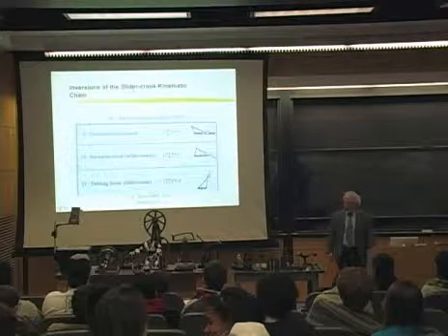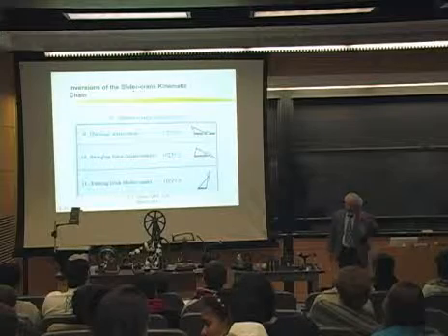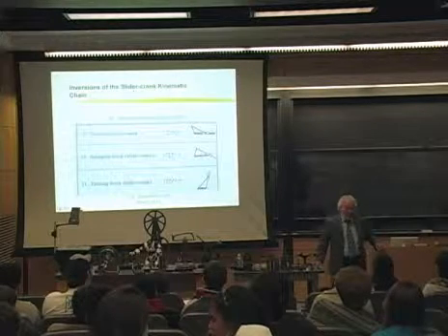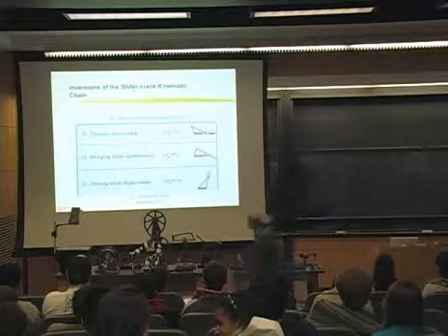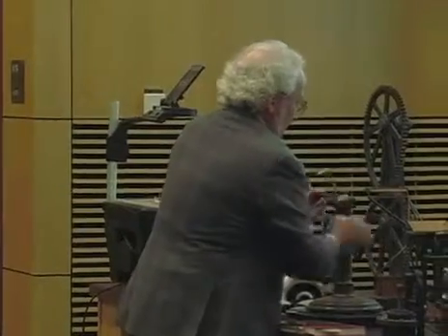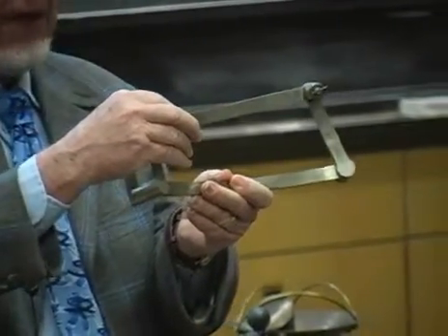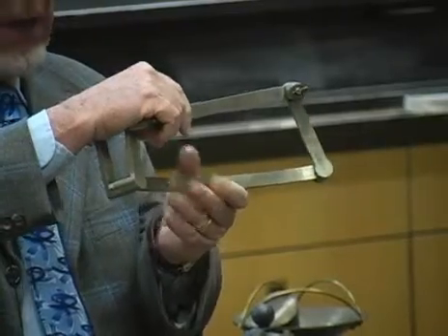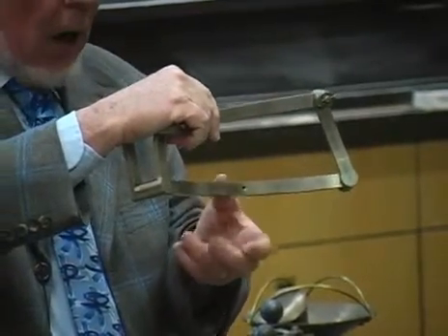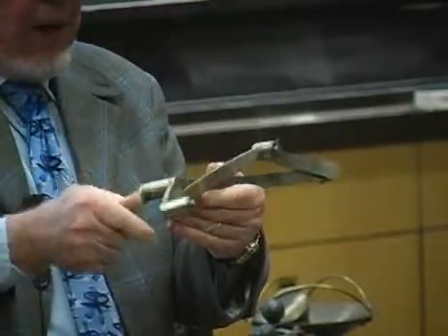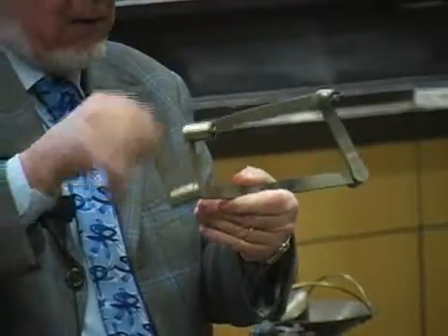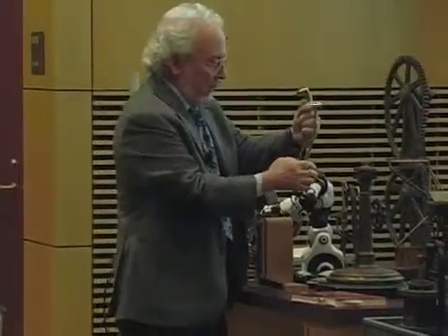Now, one of the ideas here is the idea of inversion, and that's the idea that even though you have a certain kinematic chain here, so here we have 4 links and 4 joints, the types of motion that you can get out of this depends on which one you ground. In this particular one, we just ground this one here, and when we grounded this one, we had this so-called crank rocker. But we could decide to ground one of the other links.